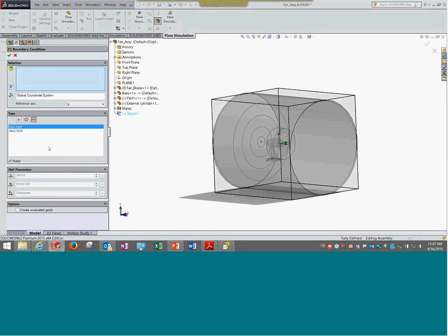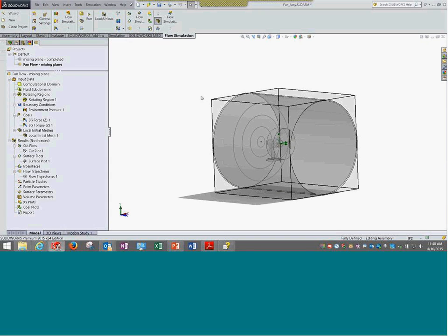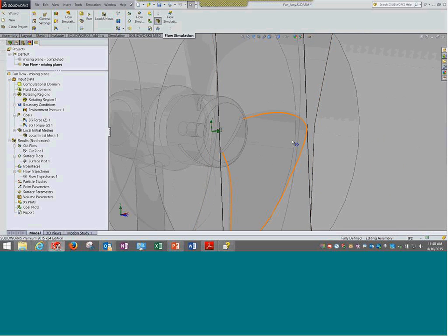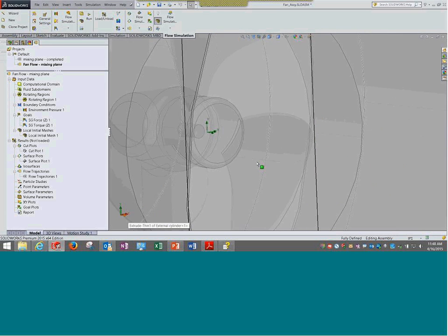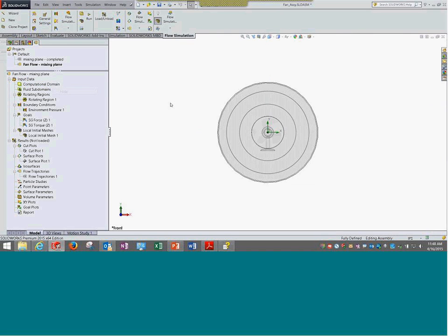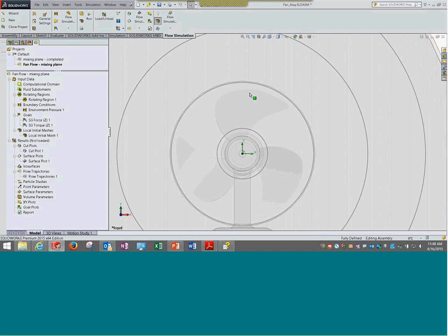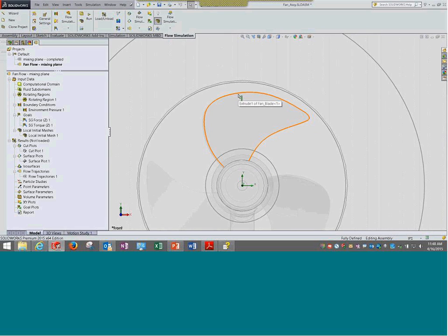And there are at least 2 to 3 elements after the blade. So if the blade is ending at a certain location, can I take a standard view? Or can I hide the domain? Yes, I can. So if you open here, the blade ends somewhere here, and we do have this gap. So this gap needs to be maintained to ensure that you capture it accurately, even though this gap may be overlapping with something that is static.